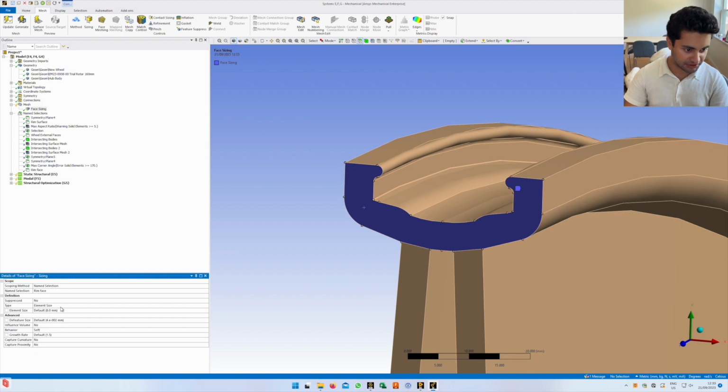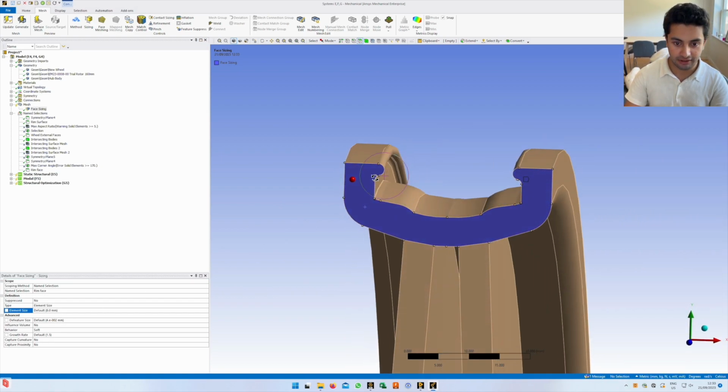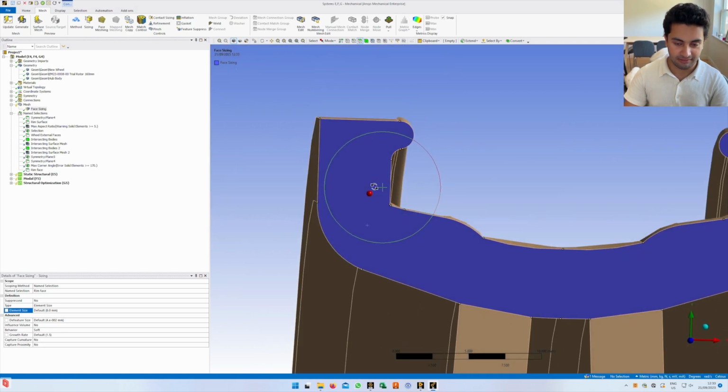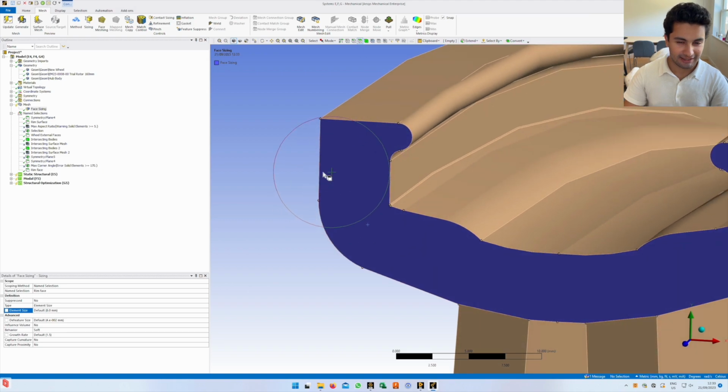Then we've got a few other options. So element size, we can change that. Your cursor will actually show you this radius here that's following my cursor is the size of the element. So right now it's at the default, which is 8mm, and you'll see that's really quite large. Now, when sizing mesh elements, you want at least 2 elements in each dimension.